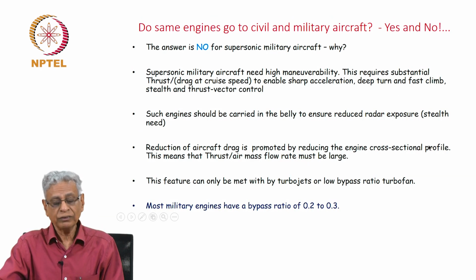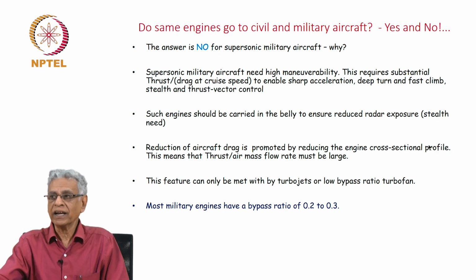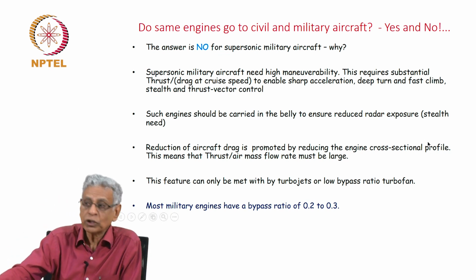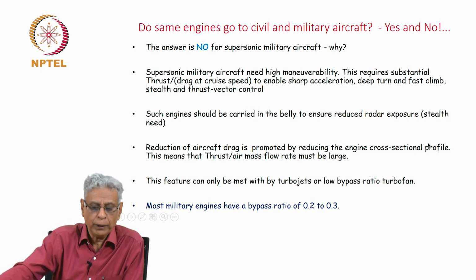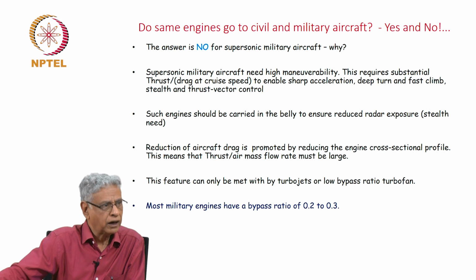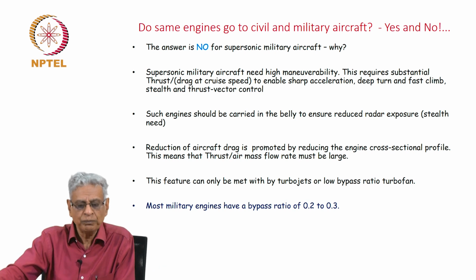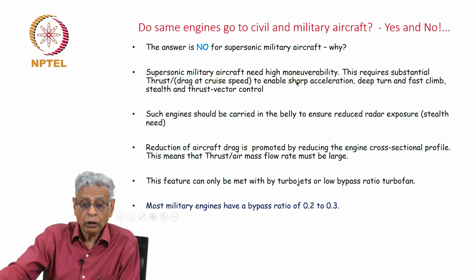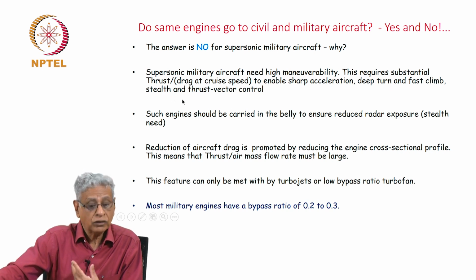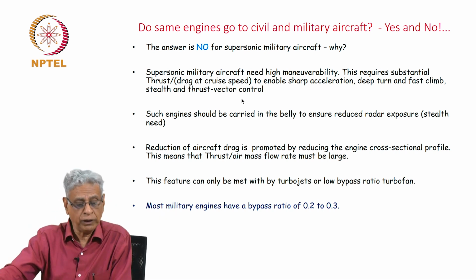Now, let me ask the question with respect to supersonic military aircraft. Is the same true? No. And why? Supersonic military aircraft need high maneuverability. This requires substantial thrust to drag at cruise. The cruise is to be defined carefully in military aircraft. There is some regime which is considered on speed, and that is considered cruise. But you want sharp acceleration, deep turn, fast climb, stealth and thrust vector control. All these are features of a supersonic aircraft meant for military applications.